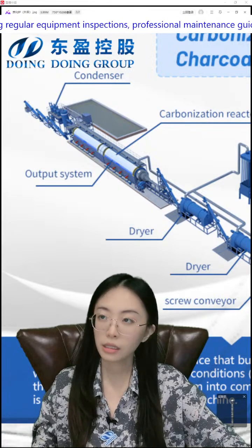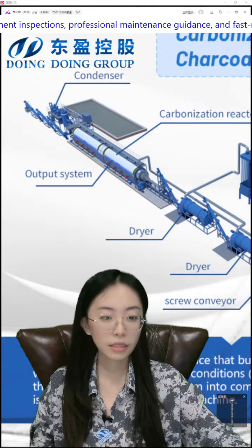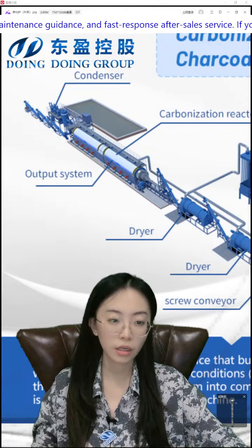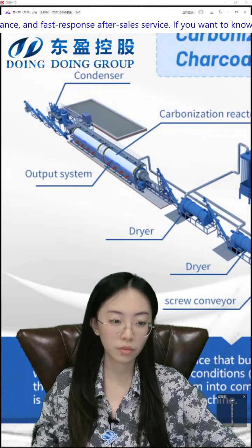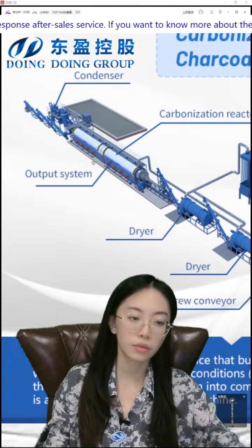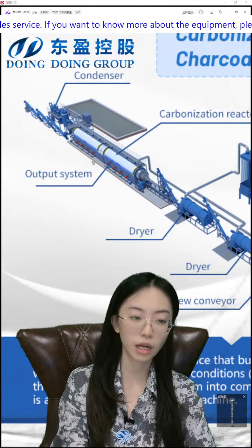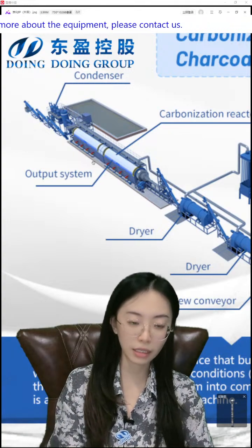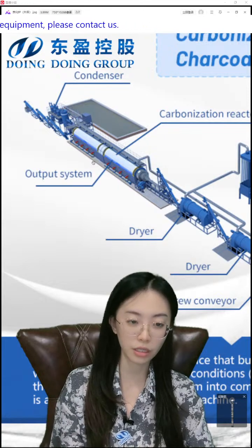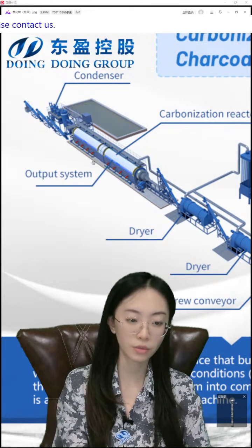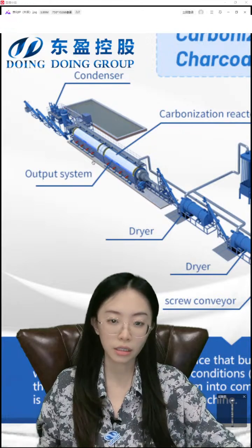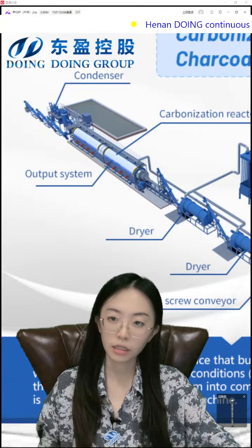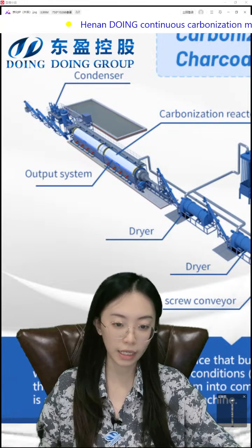Here is the slagging winch, and then the gas that we get from the carbonization furnace will be cooled from the rear outlet. From there it will come to the cyclone dust collector. The first purpose is to purify it and lower the temperature. Then it will pass through the hot wind furnace for combustion and heating, which saves energy of the heating system.